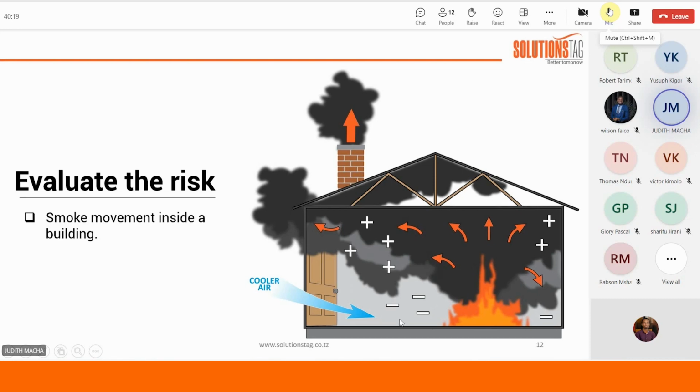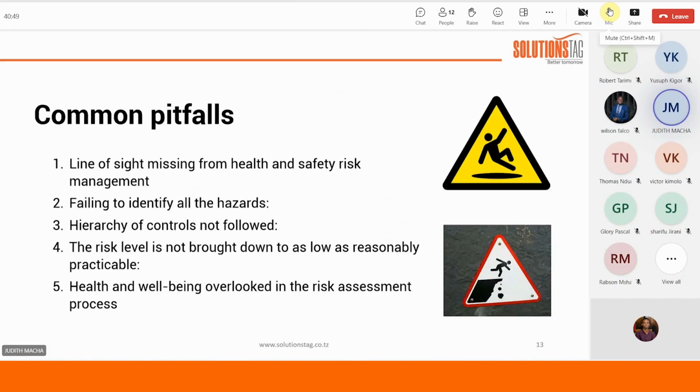And the emergency door, can they access it at the point that they need? Which way does it open? Is it opening inward or outward? You need to understand. If there's smoke and someone faints due to smoke, and the door opens inward, somebody can fail to get out. But if the door opens outward, then somebody can crawl and push the door, and they can go out, and we reduce the risk in that area.